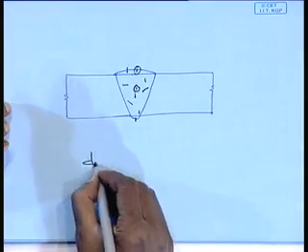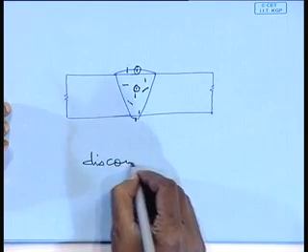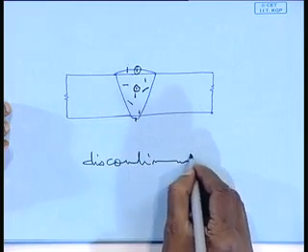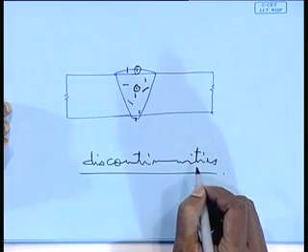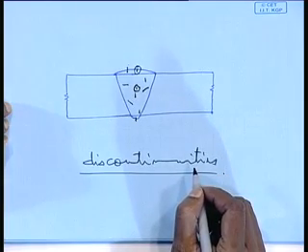In generalized terms, we are talking about flaw. It can be a crack, it can be something else, it can be a foreign particle lodged inside the molten metal. That is also a discontinuity. A crack is essentially a discontinuity. So, we will essentially look for discontinuities inside a welded joint.